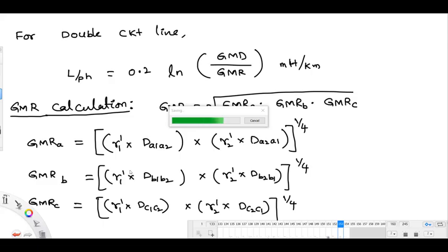What is proportional to square? In a parallel transmission line, L will be independent for each circuit. You can calculate L for circuit 1 and circuit 2, then connect the two inductors in parallel.